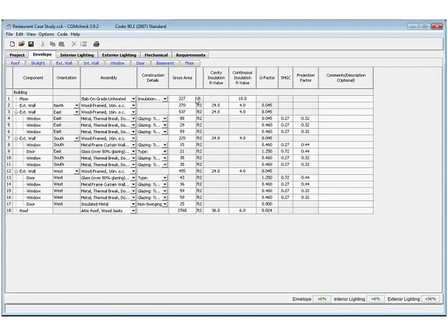Let's come over to envelope, and here's a typical restaurant and their takeoffs. They have a slab on grade, and they've defined it, and they're insulating it. You know, there's exterior walls, and what they've done here is separated all the exterior walls out and shown the orientation, and also put the appropriate windows and any doors under each wall. They've defined out the assemblies, the construction type, cavity and or continuous insulation, any overhangs, which they've put in here as well. They've put the roof in and what they're insulating it to. This is something a plan reviewer, when they're looking at it, they're going to go through and check all these. But as a user, you'd want to double check them too.